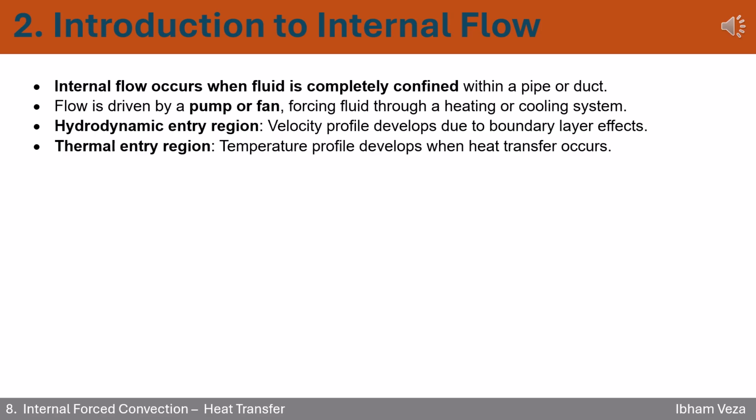In these cases, flow is pushed by mechanical force, a pump or a fan forcing the fluid to move through heating or cooling equipment. You'll also see 2 important regions. The hydrodynamic entry region is where the fluid velocity profile is still forming as the boundary layer grows from the walls. Meanwhile, the thermal entry region is where the temperature profile starts to settle as the fluid heats up or cools down. Internal flow is what powers modern energy systems, from power plants to refrigeration units, so understanding these regions helps you build more efficient designs.